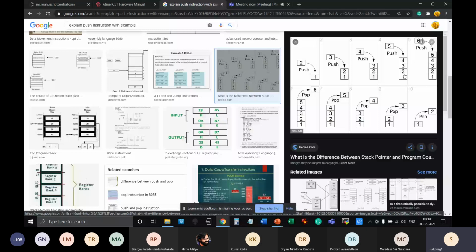Let's say you have stored up to 5 data on top of each other. That means these are different data values, kept in subsequent memory locations in increasing order. The lowest one has the smallest location address, and the top one is +5 from the lowest. The stack pointer will always point to the highest position at any point. So with every push instruction, the stack pointer moves one memory location higher.